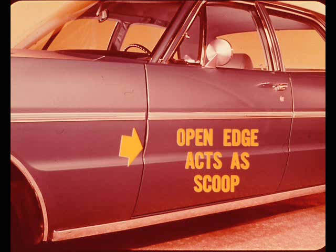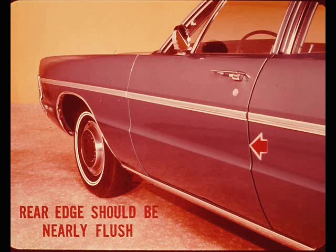How about the rear edge, Al? The rear edge of the door should also be nearly flush when the door is fully latched. If the latch striker adjustment is not correct, the door may not close properly. This can prevent good seal contact or may result in weather strip damage.